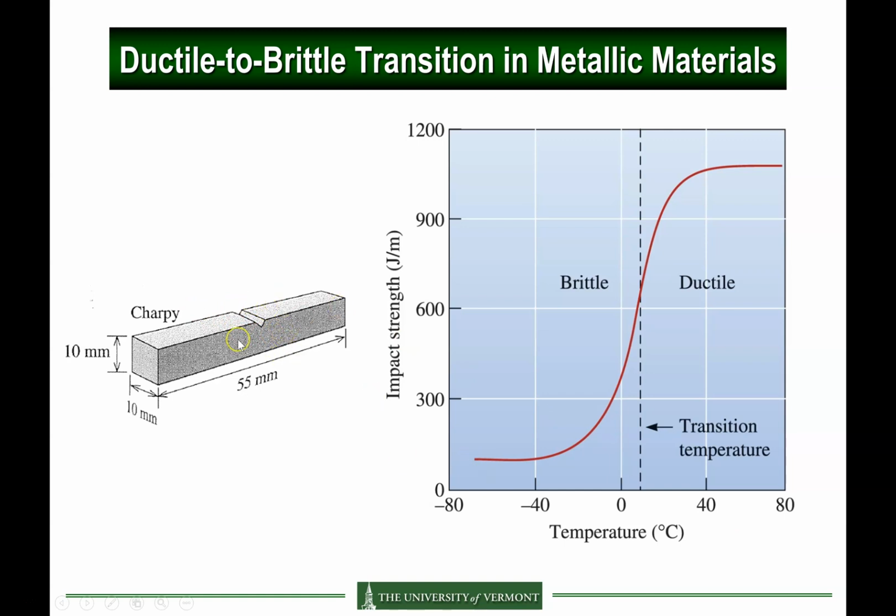And so we repeat this test at different temperatures, from low to high temperature. During the event, the hammer breaks the specimen, and some energy is absorbed to break the specimen. At low temperature, it takes very little energy to break the specimen because the specimen is brittle. At a higher temperature, it's going to take more energy to fracture the specimen because the fracture is ductile.